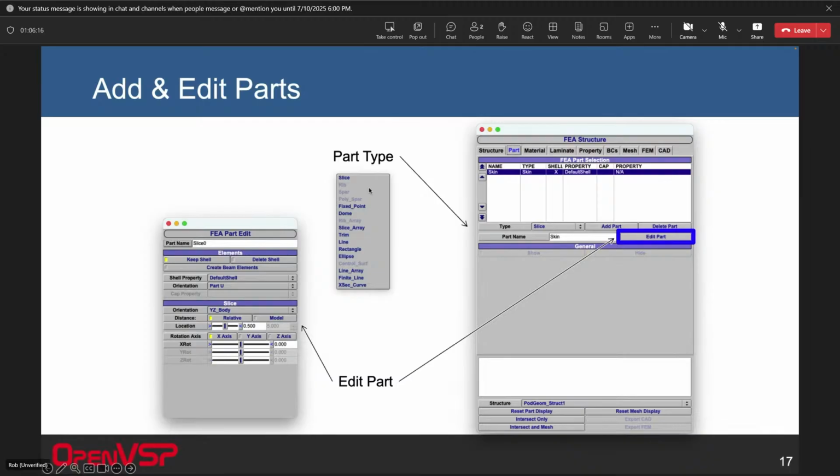You'll see that in this part list, some of them are not highlighted or are grayed out, I guess. That's because those grayed out ones only apply to wing type parent geometries. So the parameterization of ribs and spars are specific to wings, and so those parts are only available for wings. Since this is a structure on a pod, we don't see them. If we switch over and we were instead doing a structure on a wing, then these grayed out cases would come back and we would see them.